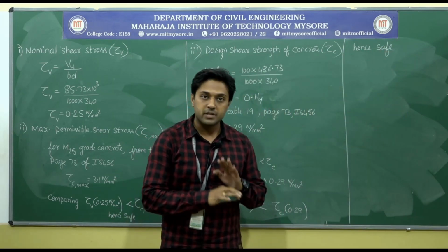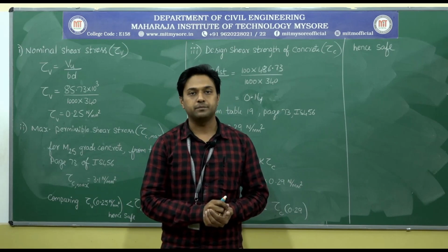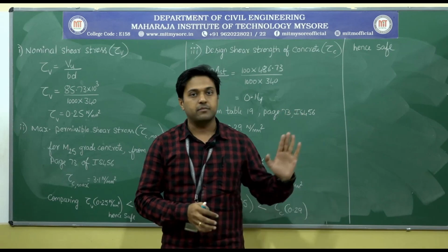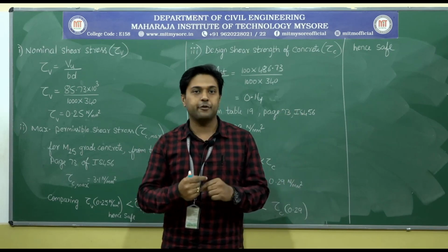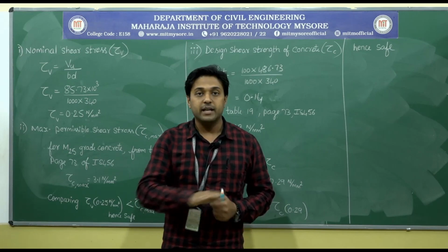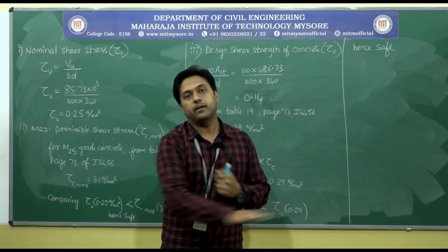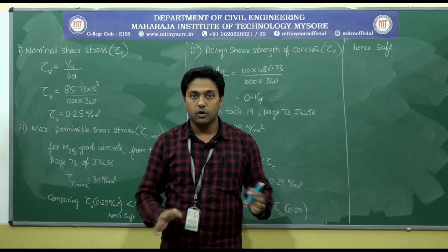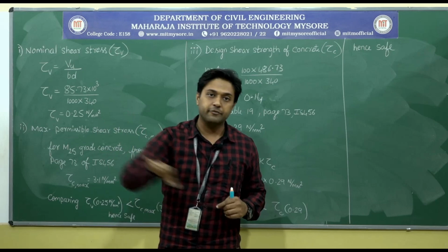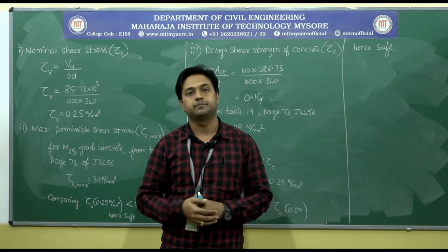So this is how we need to do it. Next would be the check for deflection. Actually we were supposed to do the check for deflection, but here I will not be doing it. The reason is that the footing is resting on the soil. As there is support from the soil, there is no need to do the check for deflection for the footing.